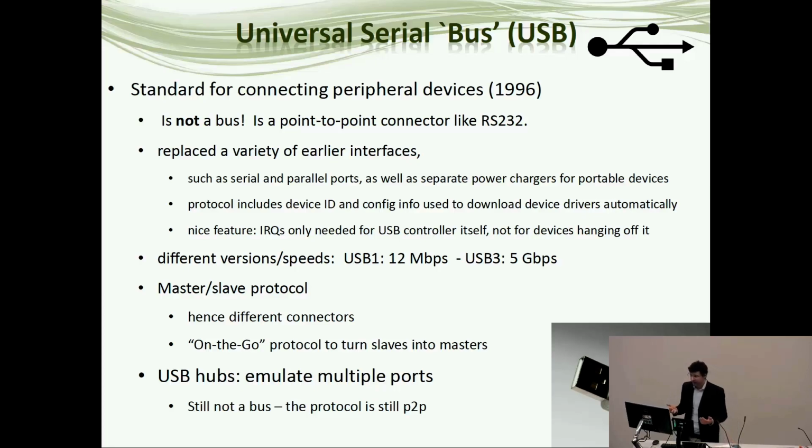So you've probably all heard of USB, the Universal Serial Bus. Bus is very much in quotes here because USB is not a bus at all. It's a completely misnamed technology because, of course, it's actually a point-to-point connector. The USB cable has one master end and one slave end. It's not a bus. It's not a public place where people share their messages. It's really intended as a modern version of the serial port, what was called RS-232. There's a way of a master device communicating with one slave device.